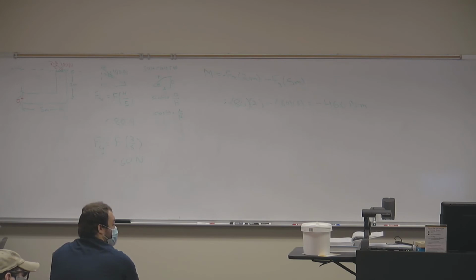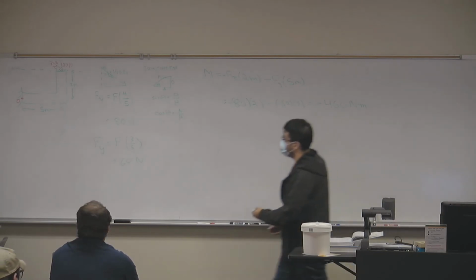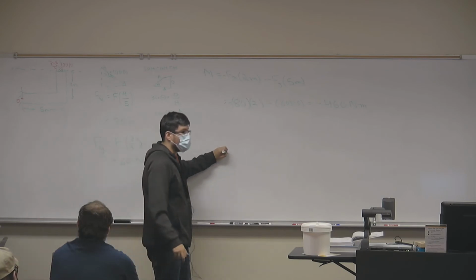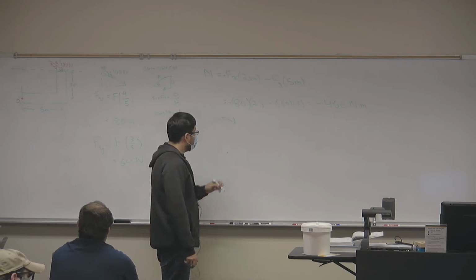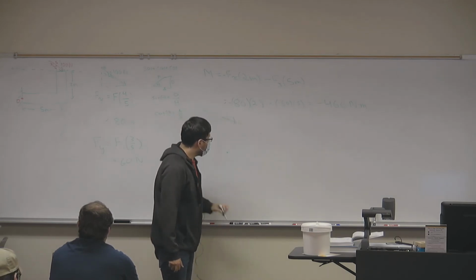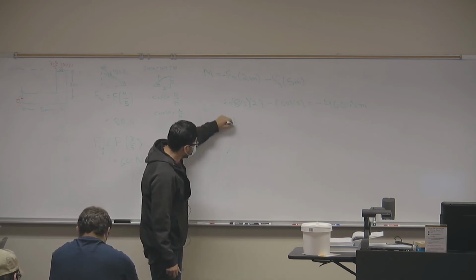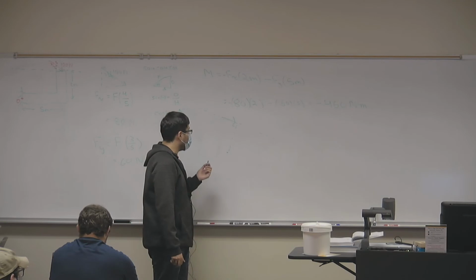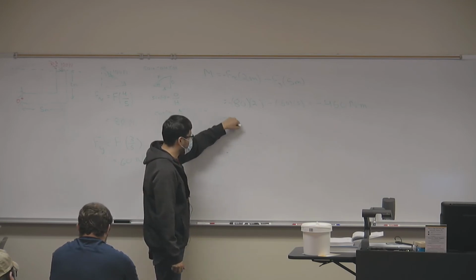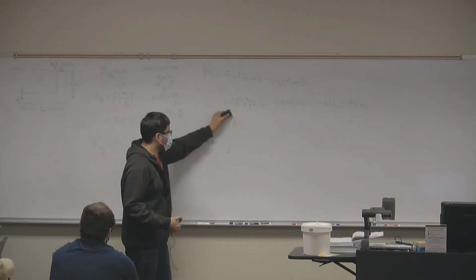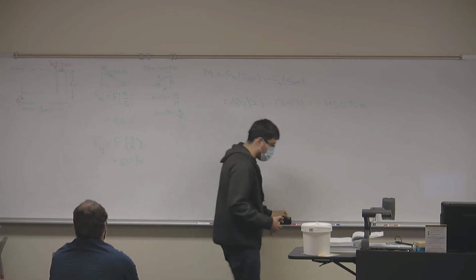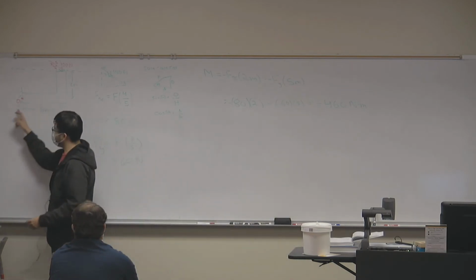Yeah? So on that steering wheel, I'm getting kind of confused about where I would set that vector for how the steering wheel is going to move. Oh, so the way I look at it is your point of interest is the center, and wherever the vector is, you just draw a circle until it touches that vector, right? So remember, your line of action corresponds to a perpendicular distance. This is 90 degrees with your line, right? So the idea is that your line of action of force should always be somewhere in the wheel, okay? But again, if that doesn't work for you, use any other method. But the idea is that you understand that clockwise negative, counterclockwise positive.